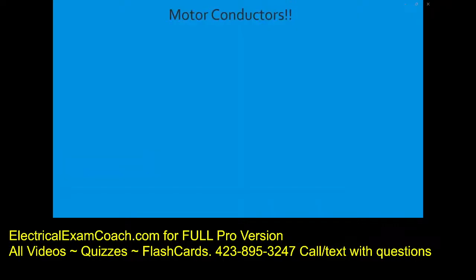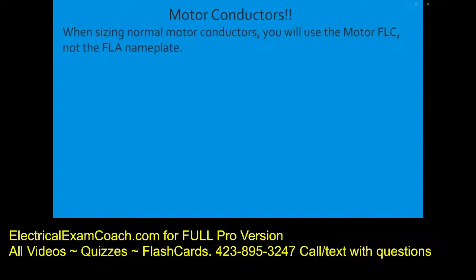Now we're going to learn about sizing motor conductors. 430 is one of the largest articles in the code book, so I'm only going to show you what you're going to be testing on. When sizing normal motor conductors, you will use the motor FLC and not the FLA nameplate. FLC stands for full load current, and that's a value that we find inside the code book. The FLA nameplate rating is typically the amperage value that they've stamped on the motor's nameplate.